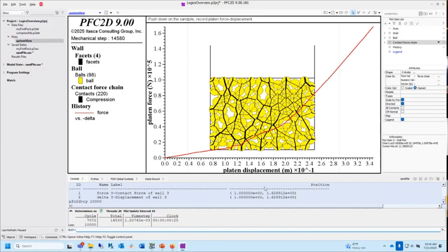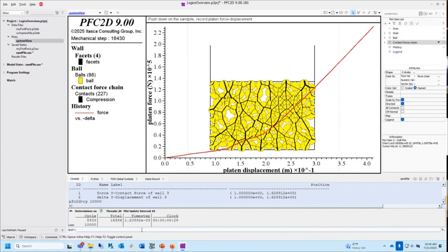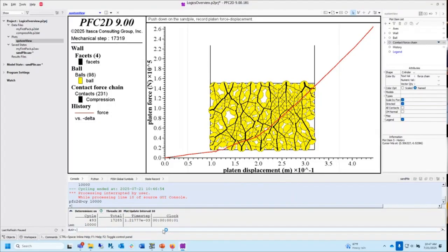Stiffness is the more contacts, the stiffer, the lower the porosity, the stiffer it's going to be. And as the contacts don't change anymore, this packing now has a certain stiffness. So basically, as it begins to load, it gets stiffer as more and more contacts form until it gets to a state where there can't be more contacts forming, and it just keeps going up. All right? You with me? Make sense?